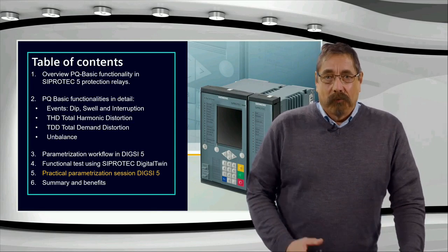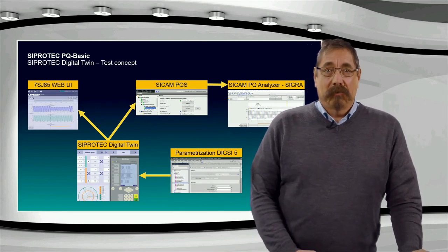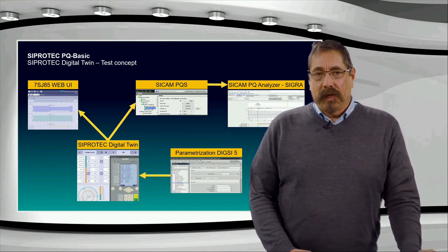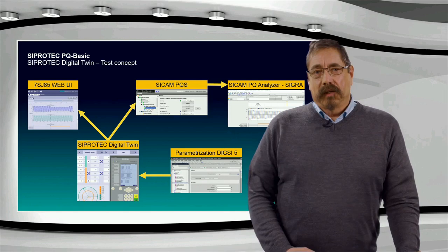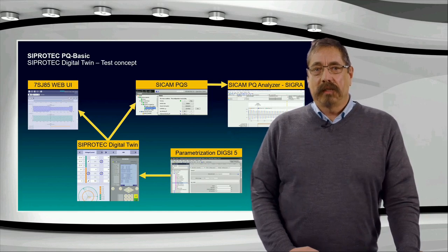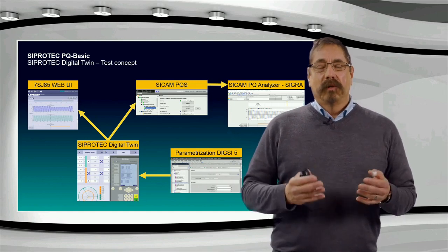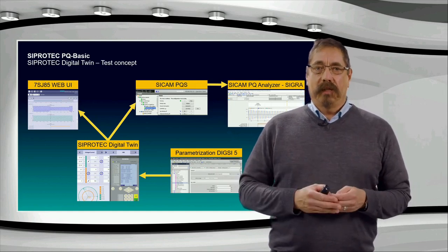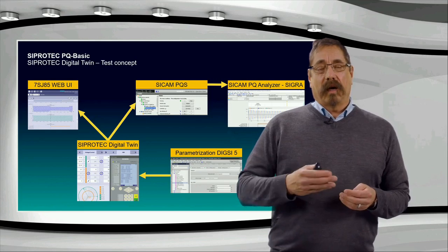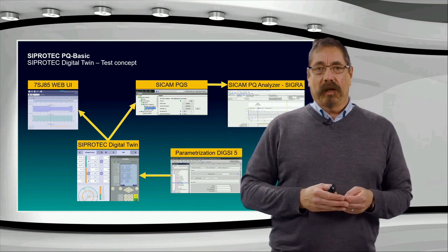All right. So once more, a short overview for the practical session with DIGSI, Digital Twin, CCAM PQS, PQ Analyzer, and Web UI. We can see here the components. We will parameterize the device in DIGSI, activate the Digital Twin, upload the simulation file, connect the CCAM PQS system and the CCAM PQ Analyzer. And in the Digital Twin, we will afterwards change the limits of the voltage input, simulate a so-called voltage dip or swell event. Let us see how the virtual device is reacting, and the upload of the COMTRADE files of the fault recording with the CCAM PQS and the visualization in the CCAM PQ Analyzer.